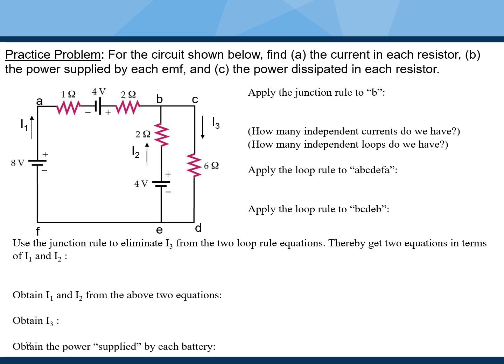So we can actually go ahead and say that applying the junction rule at the junction B out here, we have a situation where I1 plus I2, which are both coming into the junction, is equal to I3, which is flowing out of the junction. So that is just the application of the junction rule. And so we're going to basically set up a convention which says that wherever we have I3, we're actually going to replace I3 by I1 plus I2 and simplify our lives.